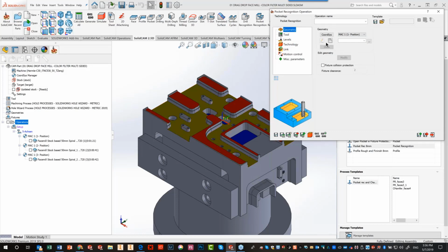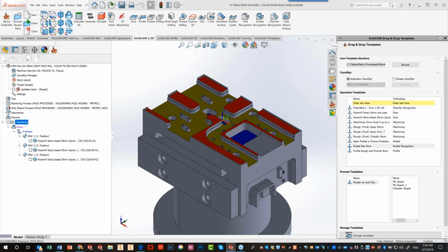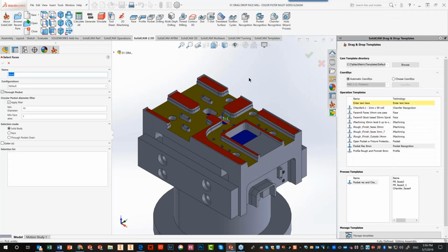And then I go to building a new geometry, identifying our features. Now, like I said, this diameter, I'd like it not to take. In other words, anything that's that size or smaller, I'd like it not to choose for the feature recognition of the pockets. Before I continue, we have here what they call circular pockets diameter filters. Right now, as a default, it says 10 millimeters.